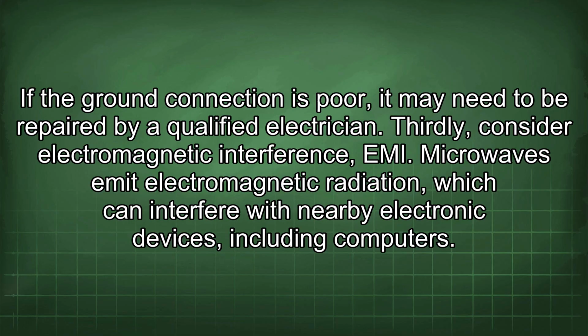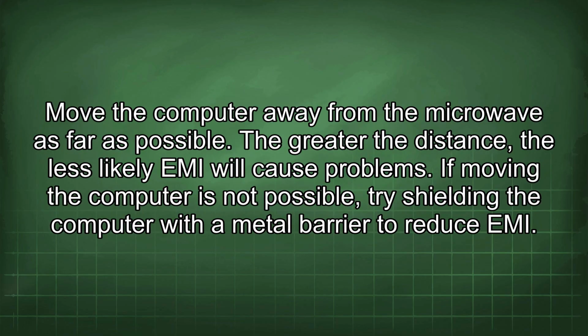Thirdly, consider electromagnetic interference, EMI. Microwaves emit electromagnetic radiation, which can interfere with nearby electronic devices, including computers. Move the computer away from the microwave as far as possible. The greater the distance, the less likely EMI will cause problems. If moving the computer is not possible, try shielding the computer with a metal barrier to reduce EMI.